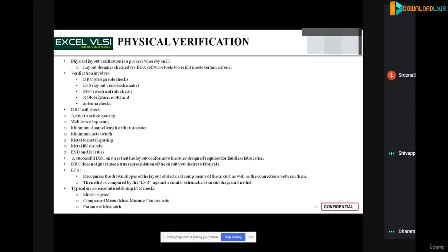So A and B inputs will be passed to the Y output after 2 nanoseconds. There may be multiple stages of AND gates, OR gates, so when you're doing timing analysis of a combinatorial circuit alone, like the multiplier some of you mentioned, you have built a multiple stage multiplier where whatever input you give will be passed to the output after the propagation delay of all the stages of this multiplier. You agree?